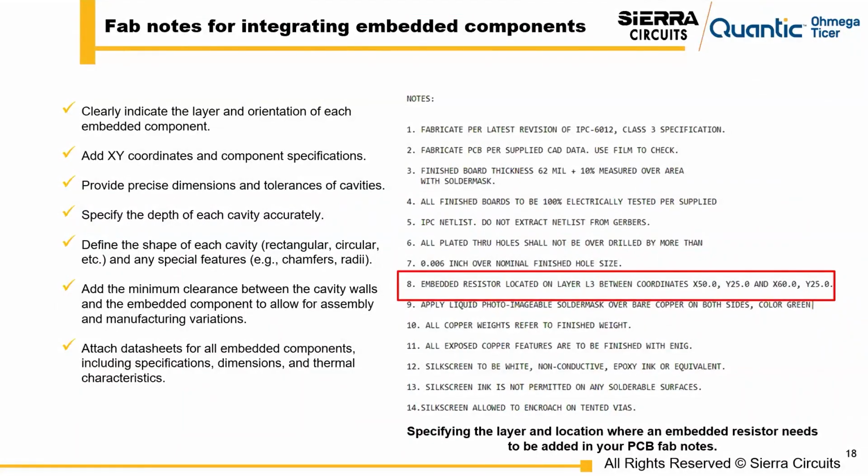And if I haven't stressed it enough, the fabricator that you choose should have experience with building these type of layers into your stack up. And it does require some attention, although not too bad. It does require some attention and process changes. So you should talk to your fabricator and kind of alert them ahead of time.